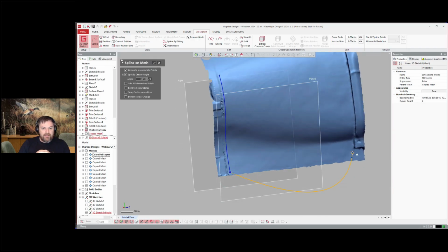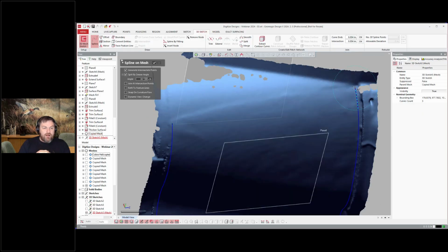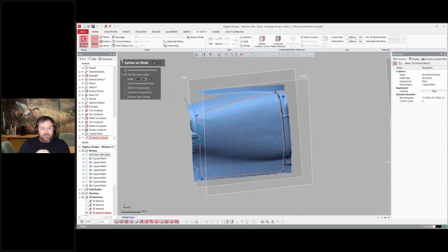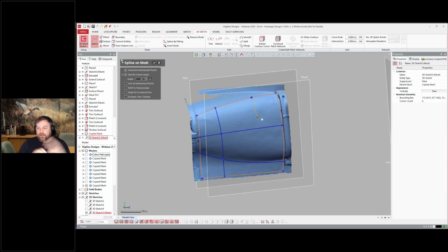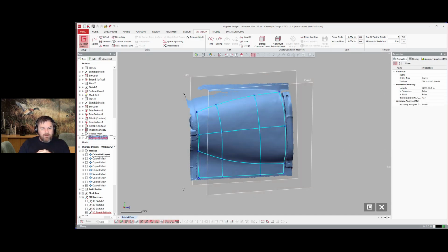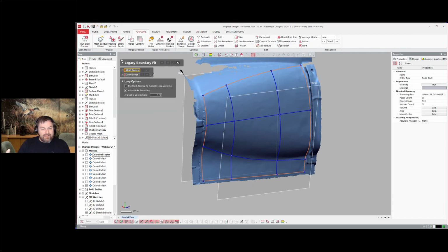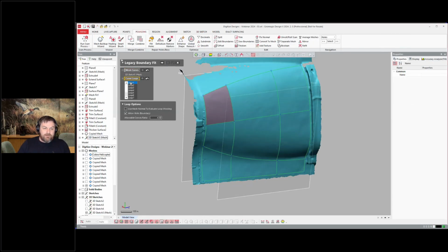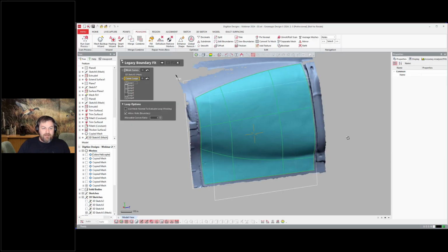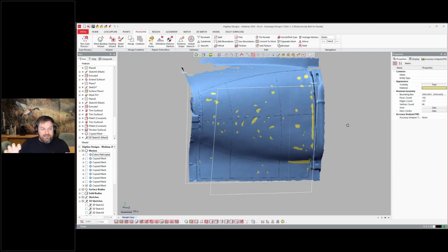So now, in this instance, I'm showing another piece of functionality that I really like to use a lot, and this is the boundary fit surfacing tool. So you can just draw 3D curves anywhere on the shape. And these are along the lines of what the original designer might have done if he used CAD or however they designed this originally, right? And I can just draw out this curve network based on the curve components here, because that's another panel there. And I can say fit surfaces to these boundaries, but yet the interior of those surfaces fits to the mesh. And you see it's editable.